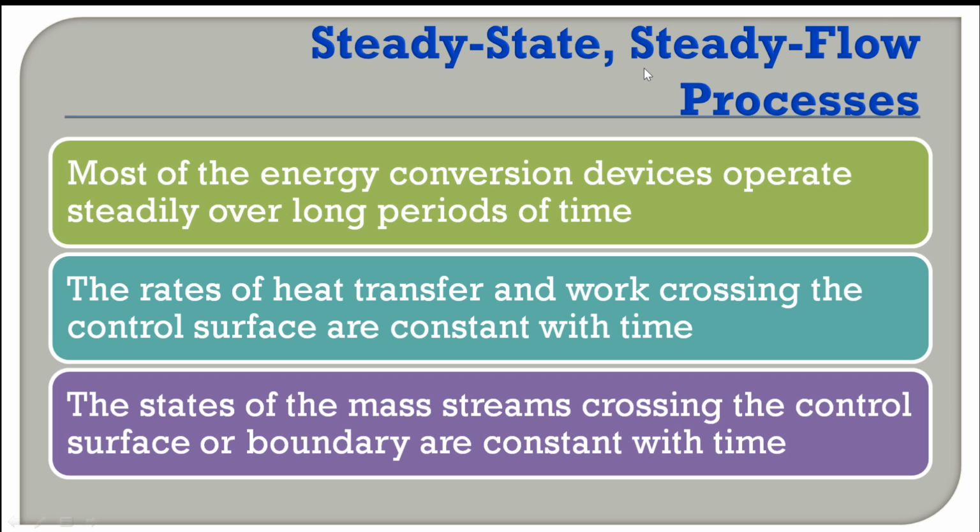Coming to the process which is well described by the steady state, steady flow process. Steady flow, you know that now. When the flow is constant with respect to time, or there is no change at a particular position in a control volume with respect to time, then that is known as a steady flow process. Steady state process: the states of mass streams crossing the control surface or boundary are constant with time. That is the steady state process.